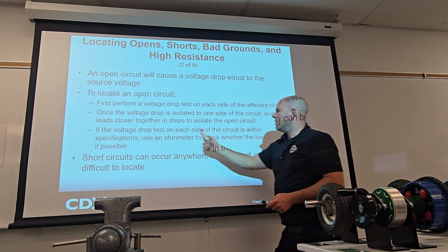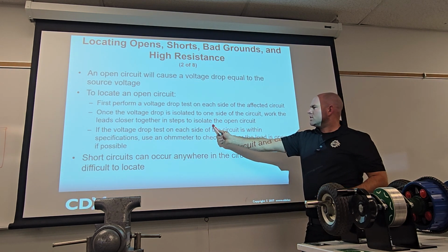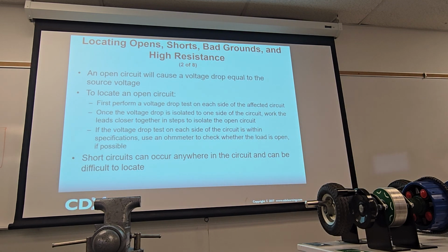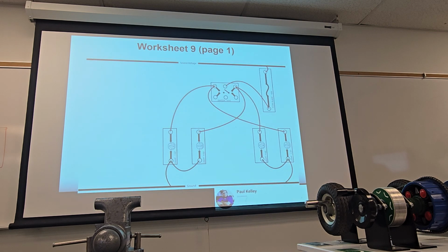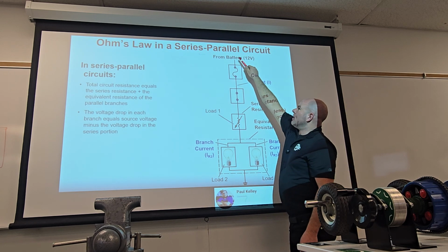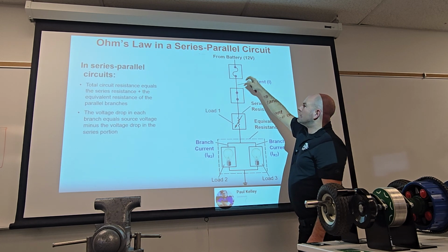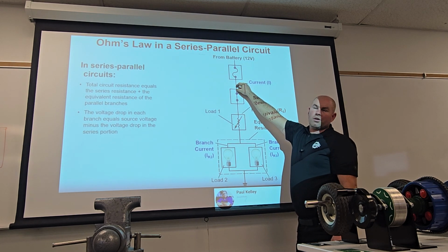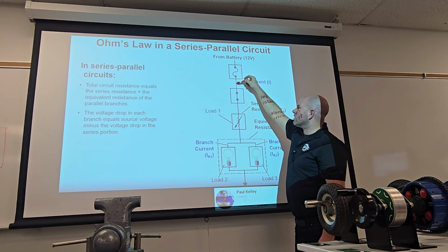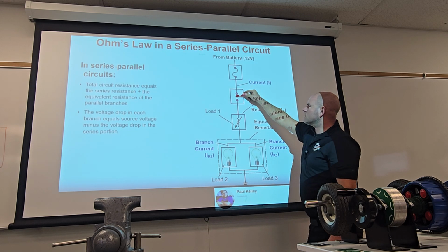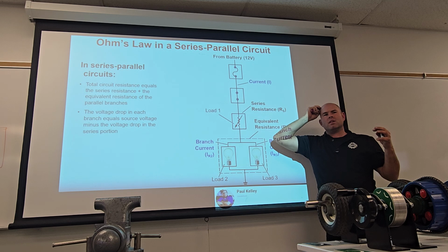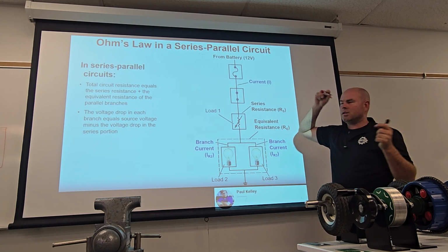As you do that, you will isolate the open circuit, right? So we're trying to say it could be all these things. If you had a problem in the circuit, it could be, in this circuit right here, this wire, this fuse, this wire, and each wire where it goes to a component has a connector, right? So technically it's actually this wire, this connector, this fuse, this connector, this wire, this connector, this switch, this connector, this wire, this connector, right? So there's a lot of possibilities. You can't guess, you're gonna be wrong. I'm just letting you know, right?